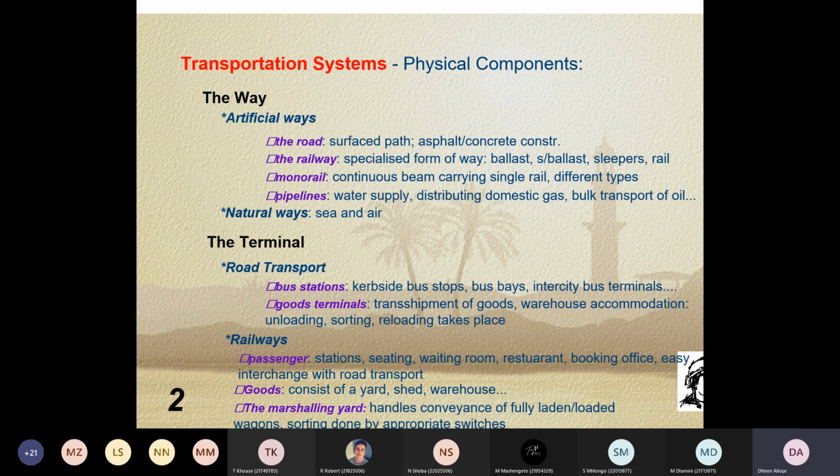Let's get back. So like I was saying, as long as your stresses on your selected subgrade are lower than the upward stresses, the carrying capacity of your subgrade layer, then you have no problem. But if the stresses are higher, that's when you get pavement failure. So with asphalt, it's your stress reduction due to depth, where you have these superimposed layers like your base, sub-base, selected layers. With the concrete slab, your rigid pavement, it's the concrete slab that does the function of stress reduction. So you don't need the superimposed layers, the design of your concrete slab.